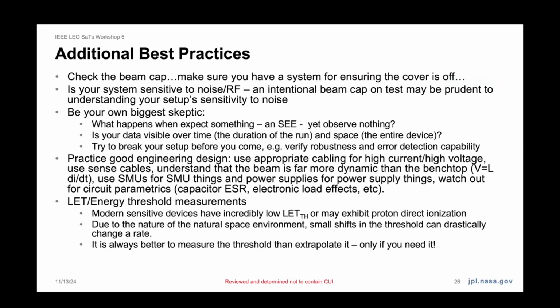A few more additional best practices and I'll wrap up here. It may sound silly, but always check the beam cap. The beam cap is there to protect the interface between vacuum and air testing. It's typically a very thin film, air mica or mylar. You pop that, it's a bad day. So we want to keep it on while we're doing a setup, but sometimes we forget and leave it on and start testing and nothing is happening and we forgot to take off the beam cap.